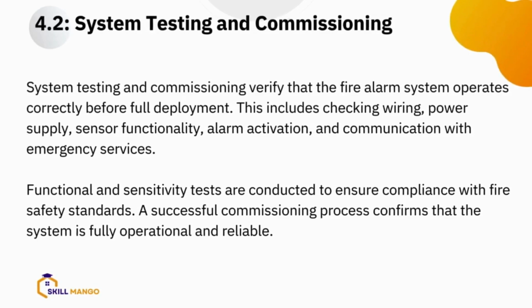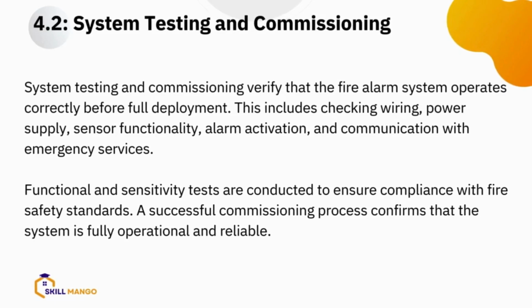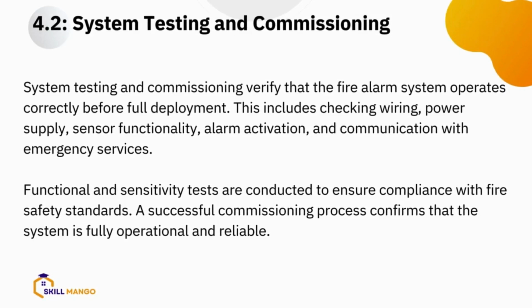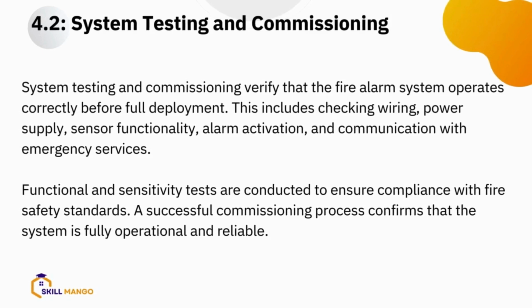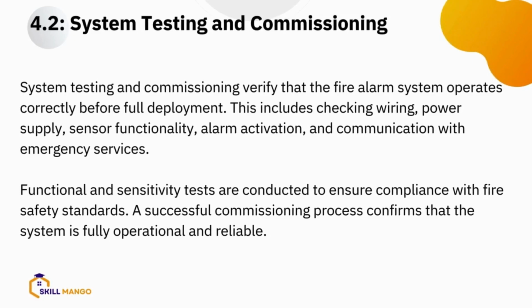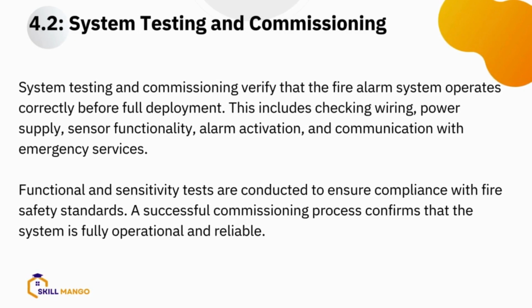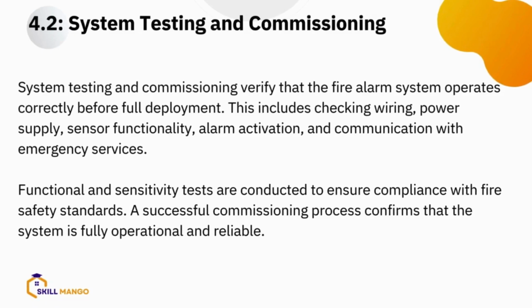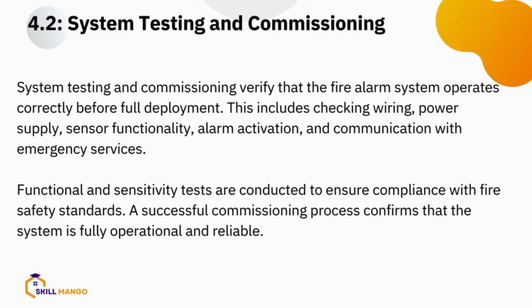All right. Then check all alarms. You have to confirm carefully and ensure that all the smoke detectors and the sounders are making that alarm. Test all the devices and ensure they are working, because you don't know where the actual fire will come from when an event occurs. So it's ideal for you to ensure that all devices are working.